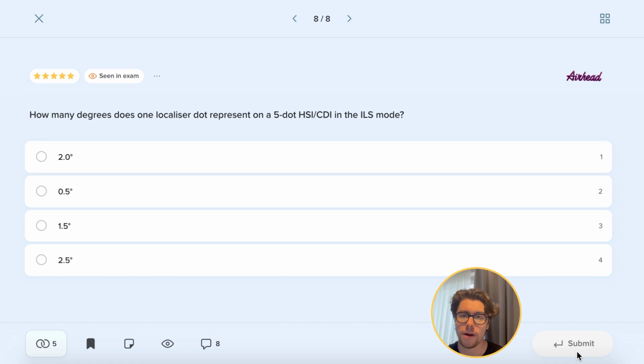So as you can see, it has a much lesser range, but it will have a greater sensitivity, because the ILS glide slope beam will show you a deflection of 0.7 degrees half scale, fully up or fully down. And in case of VOR, 1 dot on a 5-dot HSI will show you, of course, 0.5 degrees. For the glide slope, the answer would be 0.14 degrees, roughly.